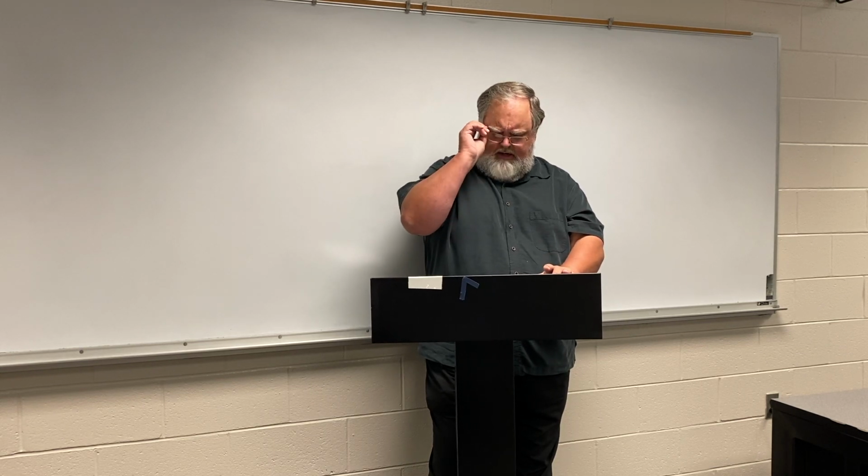Yes? So always at least 5. If you're dealing with little children, you might make it 10. Yes? Because that way you're absolutely, positively certain that thing's not gonna break. Yes? So again, breaking strength is the typical strength that is required to break the object, strength of rope or wood or whatever you're talking about. The working strength is the breaking strength divided by the safety factor.